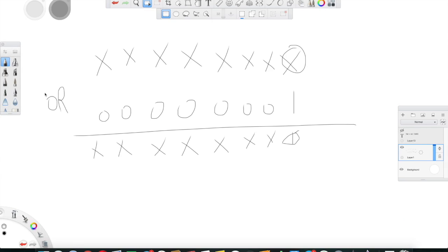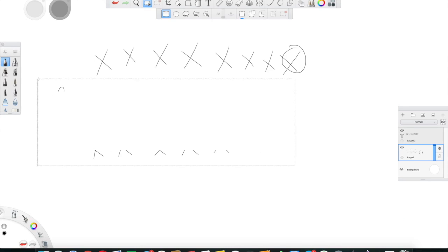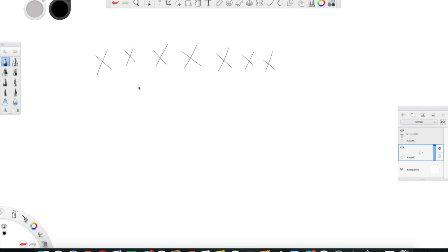Well, this time I'll be smarter and I will just delete the second part of my solution. We can delete this X, and I can add here another X. So the 4 upper bits are these bits, and I want to clear them. I will AND them with zeros, and then I will AND the rest with ones.